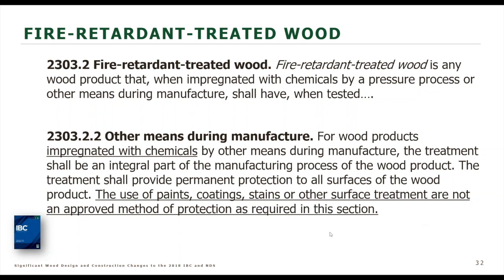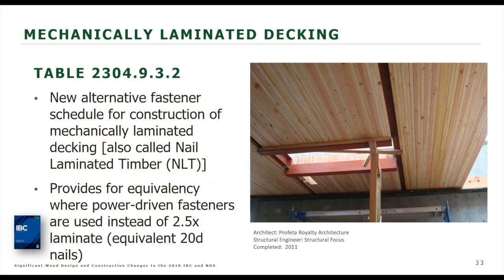In order for those to be provided as a non-combustible material, they would need to go through the alternate means approach, which is 104.7, I believe, is the section. And then the code official will more than likely request an ER report or some testing to substantiate that it can be substituted under this definition of a fire retardant treated wood. And there are products out there with an ER report.